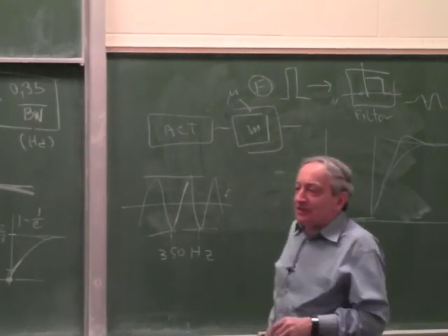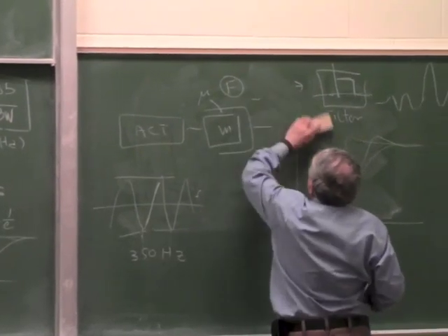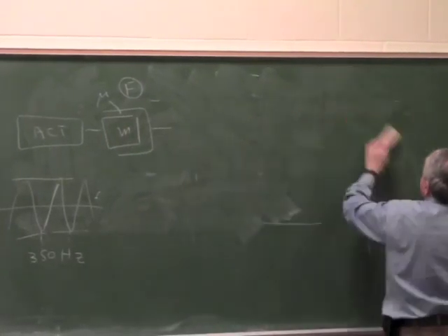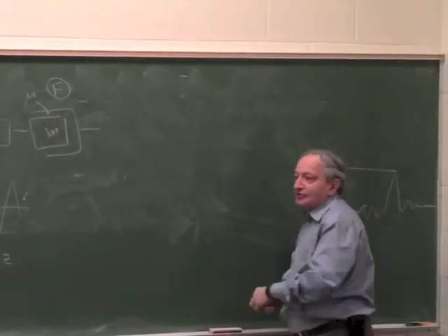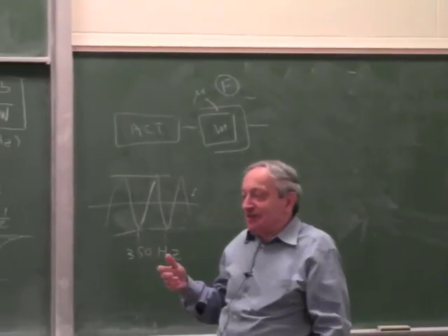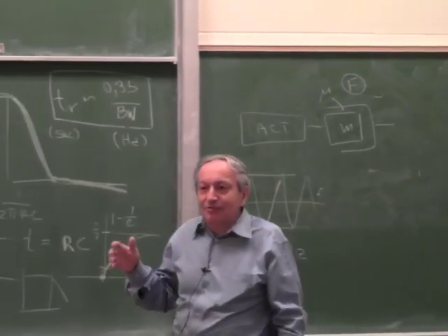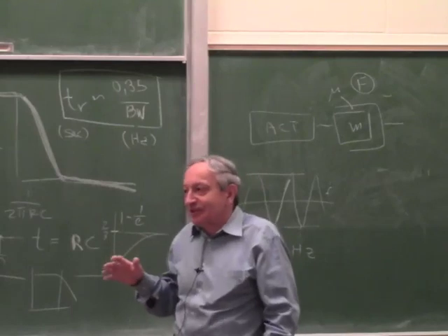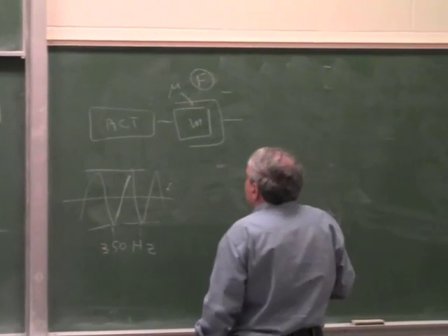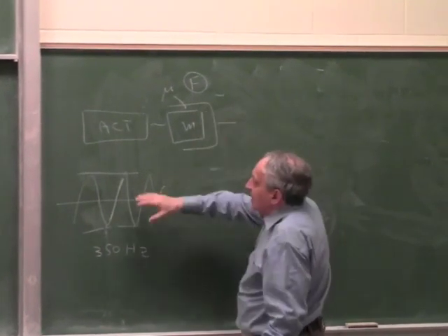If it's a complex question about power, the easiest way is to get to it through the energy. I showed you the same approach when we derived forces. When we analyzed the force of the actuator, I showed you how to derive it from energy. In a moving iron actuator, we derived the force from the energy. So in most complex problems, it's easiest to start from the energy and derive the force, the power, everything from the energy.